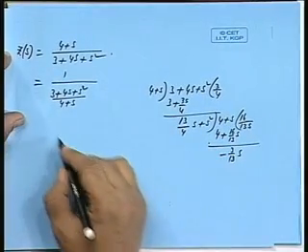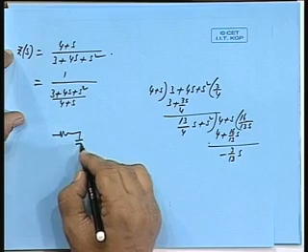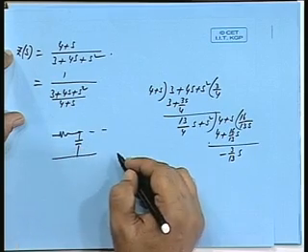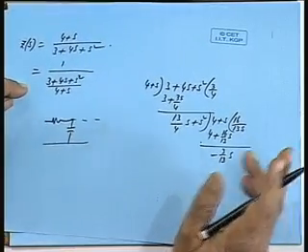That means, you cannot have something like resistance and then a capacitance and so on, then an inductance or resistance, it will fail. So, canonic forms of that kind, Cauer 1, Cauer 2, Foster 1, Foster 2, all may not be applicable here in 3 element networks. Some of them may succeed, some of them may not. As you have seen just now, I have tried all the 4 methods, and the number of elements also differ. In some cases we have got 3 elements, in some cases we got 4 elements.